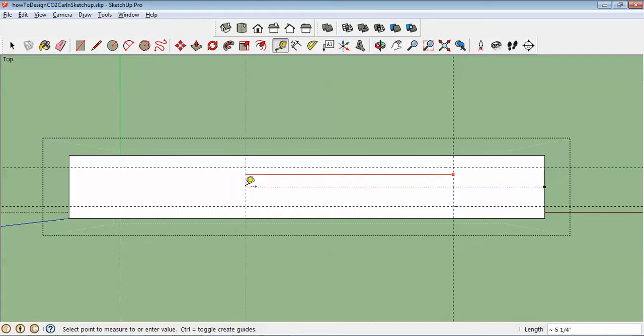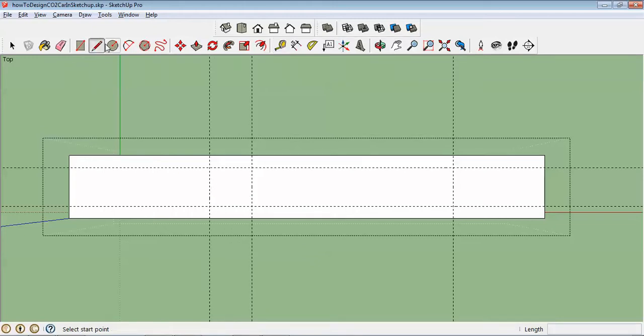Now, I'm not going to explain everything that I'm doing here, but notice that I'm using this tape measure tool to draw myself some guidelines that are going to help me know how to draw this in symmetrical. And we can talk about this in class a little bit, and I can give you some pointers. When you're using that straight line tool and you're drawing lines, you'll notice that it wants to hang on. It's kind of sticky. To get rid of that, just hit escape and it will stop trying to do that.